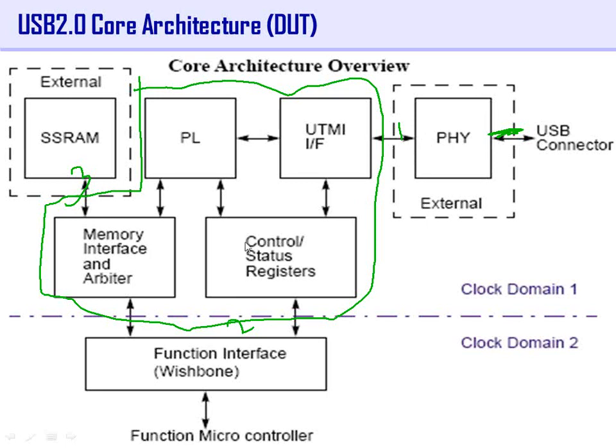What about the function interface? Ideally, in real life, when you buy a pen drive or anything, these descriptors and registers are hard coded. They are already programmed into the pen drive because the manufacturer knows why this device will be used. For a music player, he won't keep an interrupt kind of endpoint. He will only keep an isochronous kind of endpoint, so you would have programmed all that information accordingly.